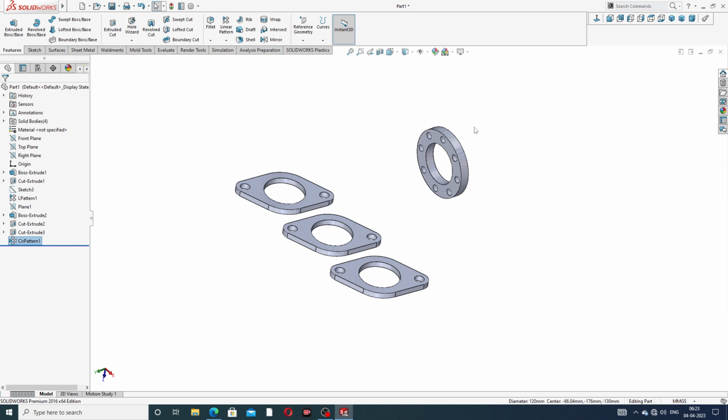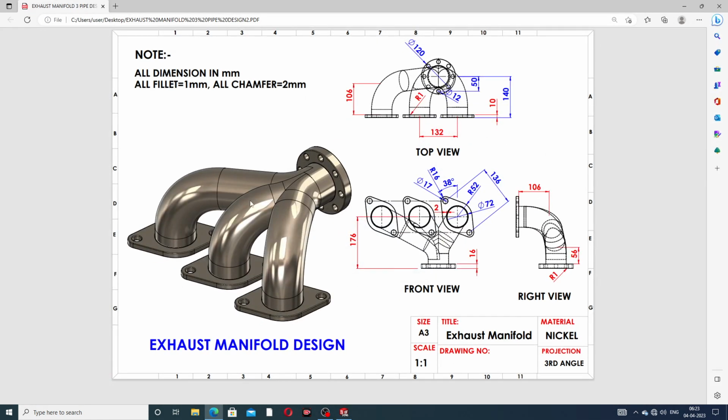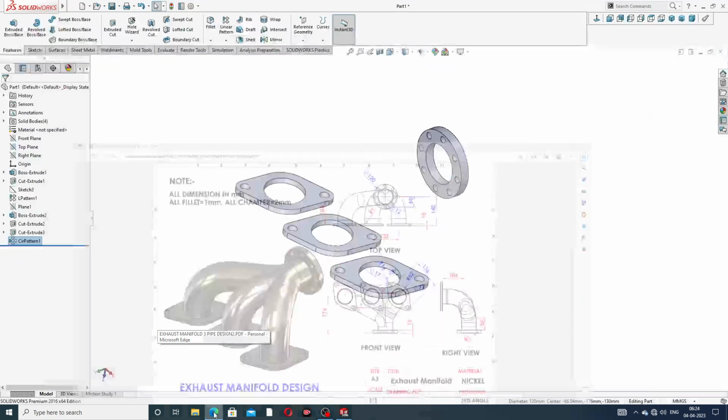Next is drawing a pipe to connect this body to this. This is very important. The distances are 160 millimeter, 106 millimeter, and 56 millimeter, and this fillet is 98 millimeter, and this is 68 millimeter, which is not mentioned here, so it is a missing point, and use a fillet.